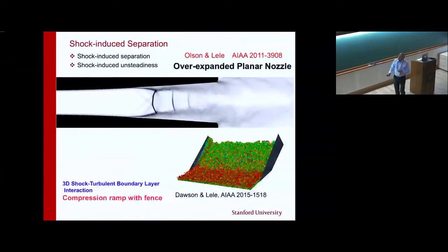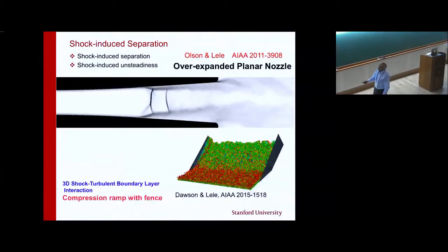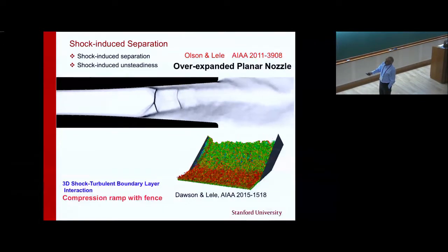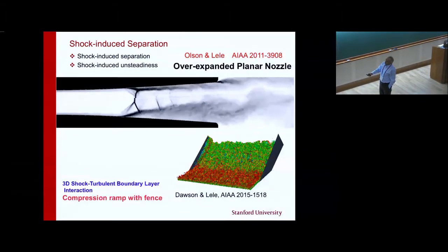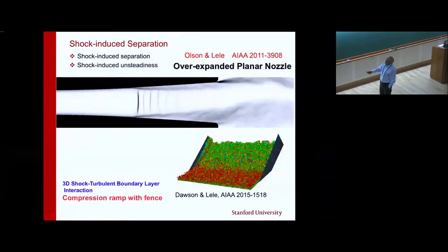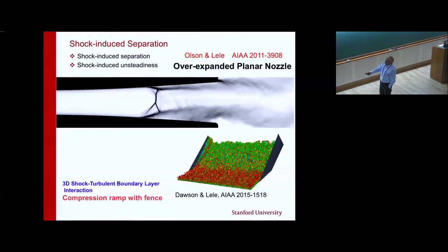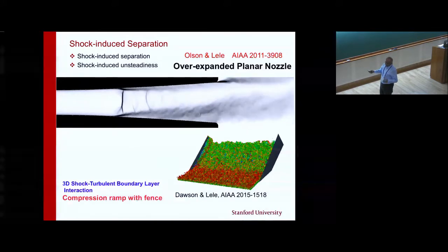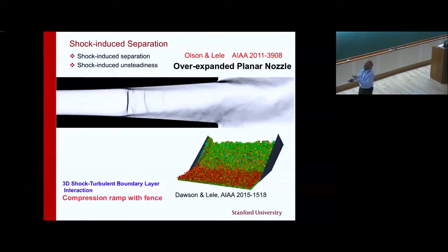Here are a few more examples. This is an example up on top of a pressure mismatched jet coming out of a nozzle. The pressure mismatch produces these shocks. Shock causes boundary layer separation. That separation moves around because the shear layer doesn't reattach, and so there is a rather large blockage produced by this low velocity region. The expansion that the flow sees is highly dependent on how much the flow spreads. This whole system is a coupled system which oscillates, and hopefully you can appreciate some of the dynamics that are taking place. This is simulations,